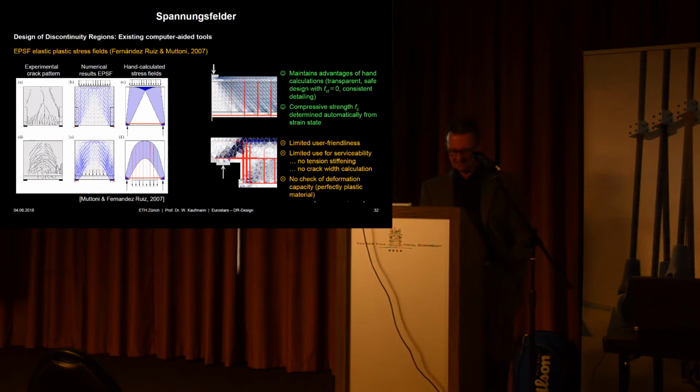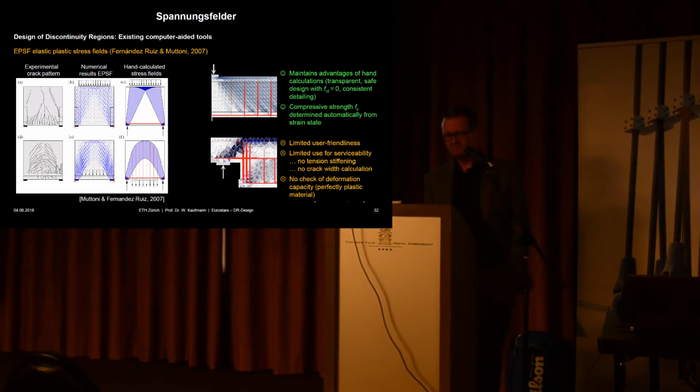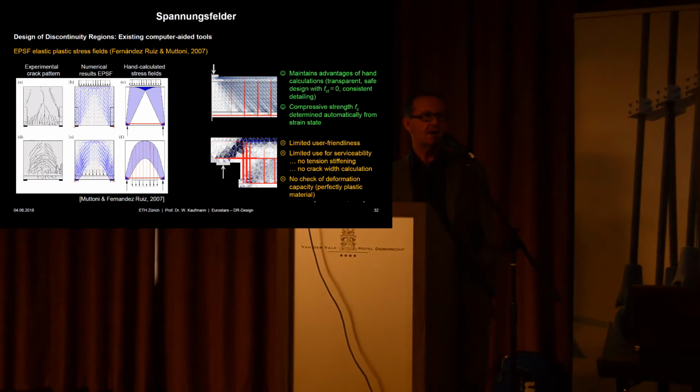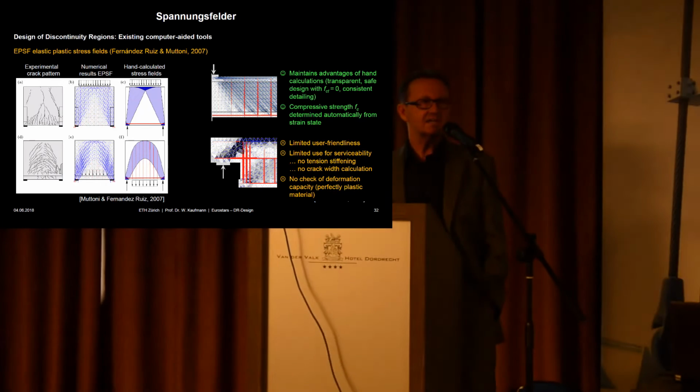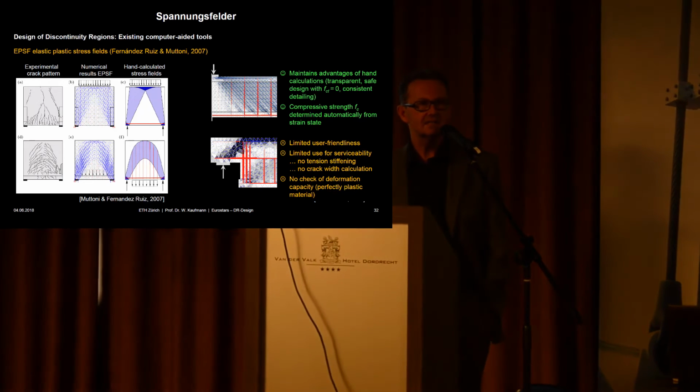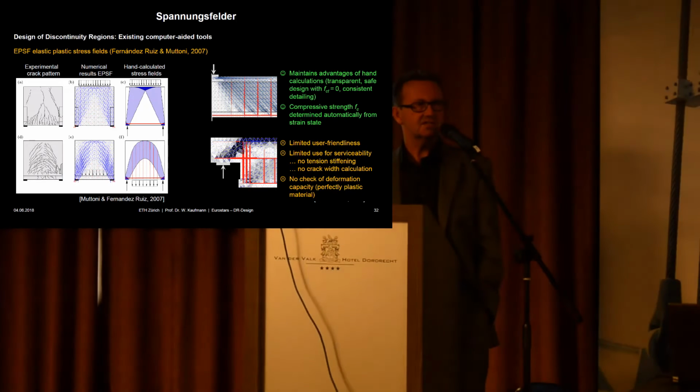I have to say that in both examples, the reinforcement is defined as a reinforcement in this direction, of course, and also horizontally it's fixed. But that's great, right? And it looks very similar to hand-calculated stress fields that you could draw on the right side. Now, why do we get strut action in one case and arch action in the other one?